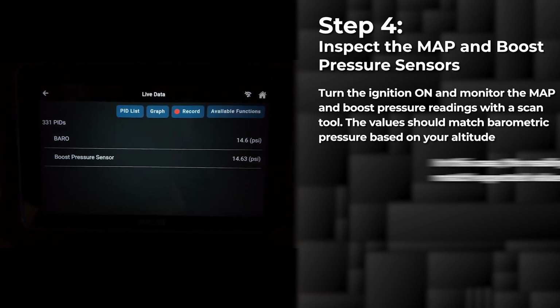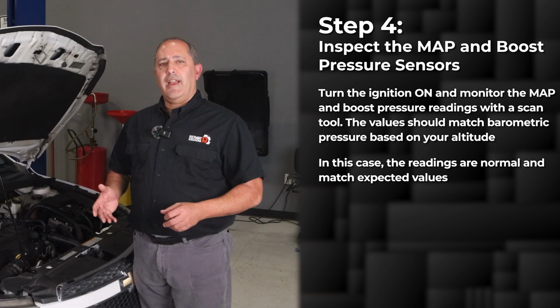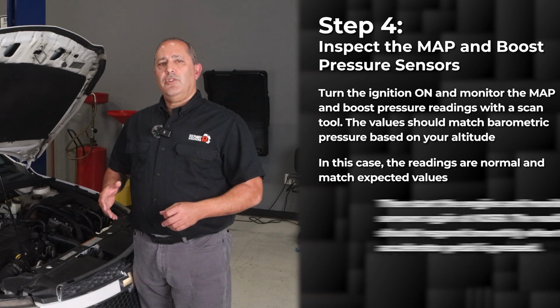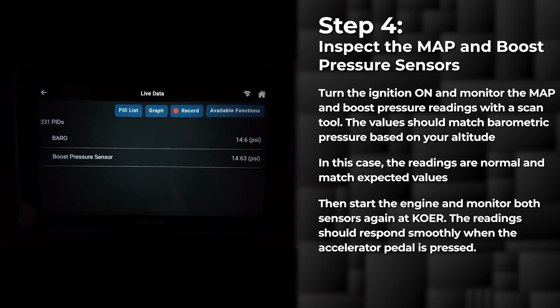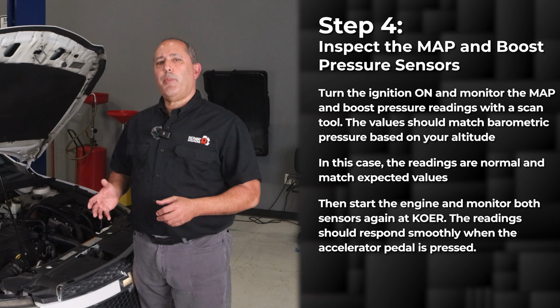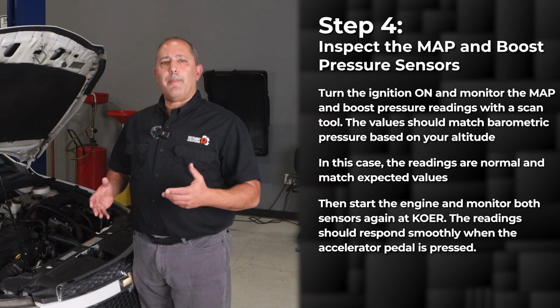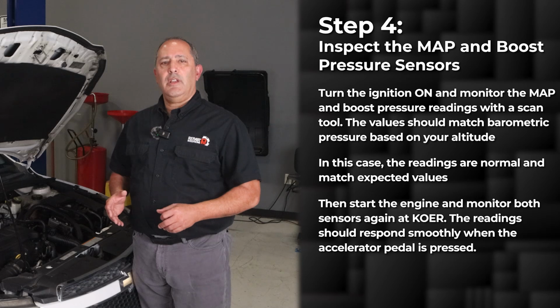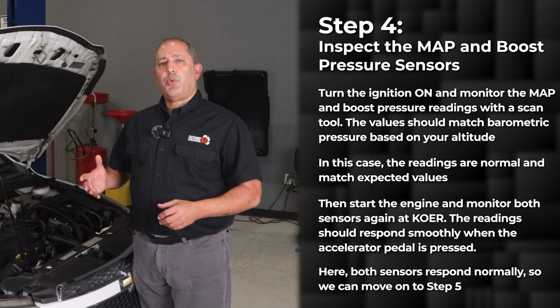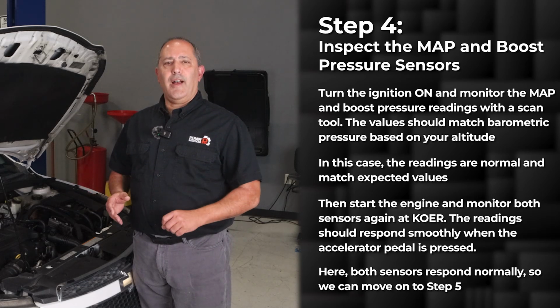If the values match, then continue on to the next step. Turn the ignition to the key on engine running position and monitor both sensors again. They should respond when the accelerator pedal is pressed. If the values do not respond properly, replace the MAP or the boost pressure sensor and then perform the repair validation. If the values respond properly, continue to step 5.